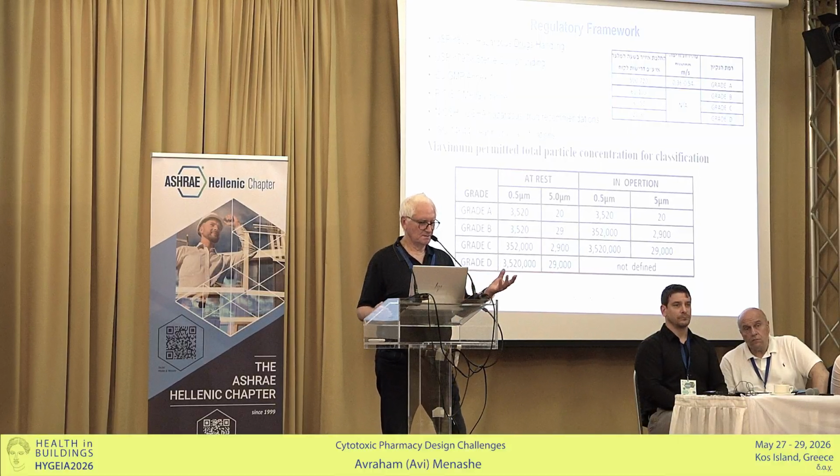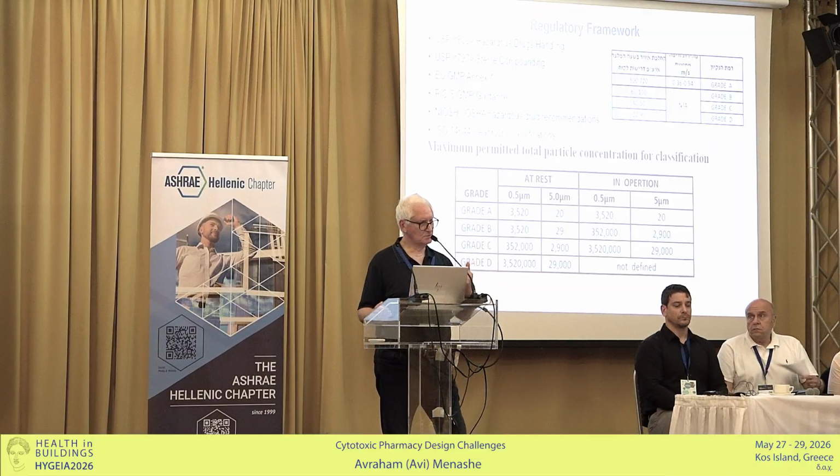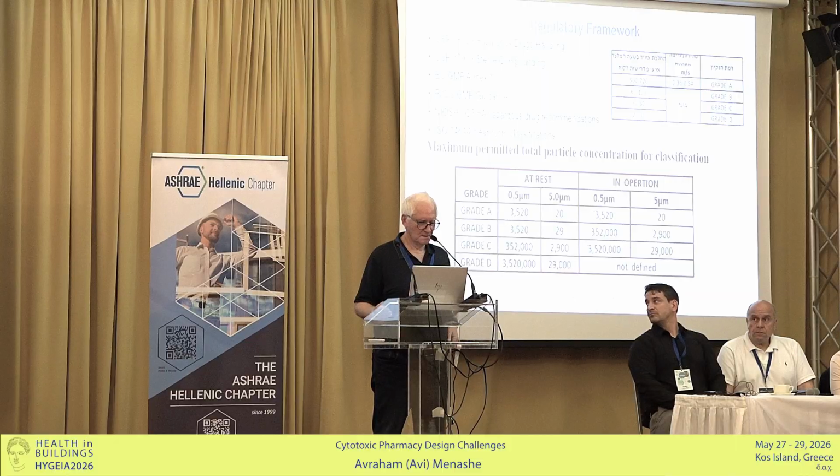Also, we classify the room and the grade according to the size of the particle in the air, at rest and in operation. It depends on the particle diameter, which is 0.5 micrometer. So at grade A, we are talking about 3,520 at rest. It's the same in operation, but as you go to the higher grades, then you have a different compromise on the number of particles that we are checking.